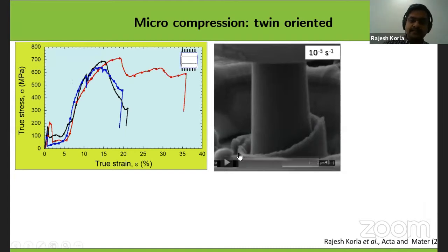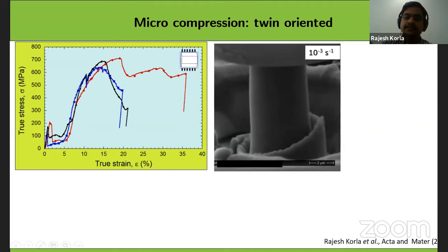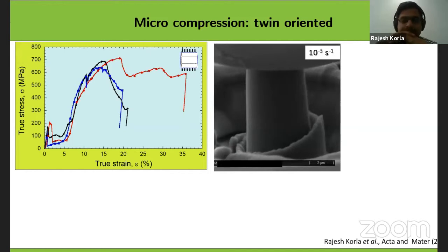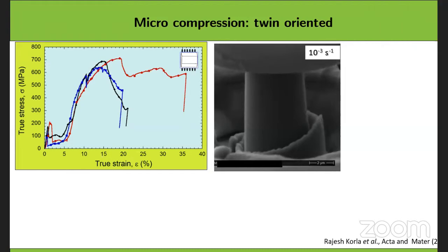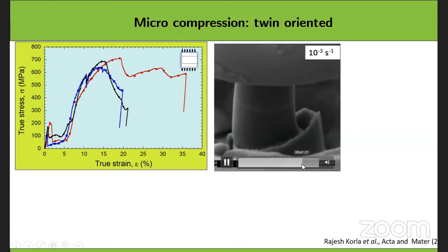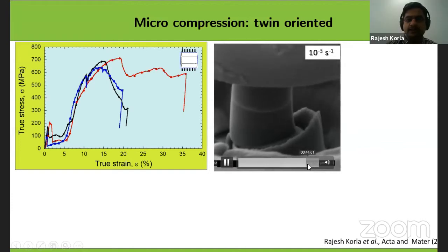But at the same time, this is basically twin oriented. Means basically you're expecting twinning. You're not seeing any slip. So when doing deformation like that, you're not seeing any slip, which is at 45 degrees of the tensile axis. Rather, it's mostly twinning. You see the twin. See, that's something, then finally going to get fracture, right?